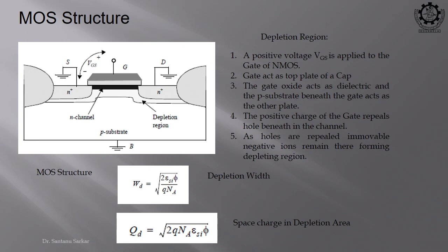Now, we are getting into how the MOSFET works. Let us think first that source and drain are both shorted to ground. So there is no potential at the source, only you are giving some potential at the gate. First tell me what will happen if I give a positive potential at the gate and this substrate is a P substrate. What are the majority carriers in the P substrate? Holes.